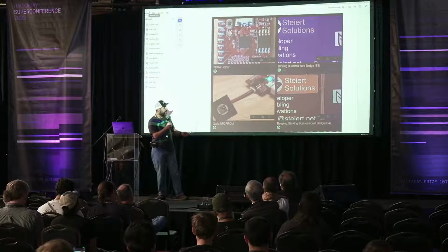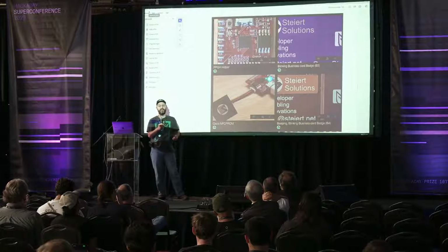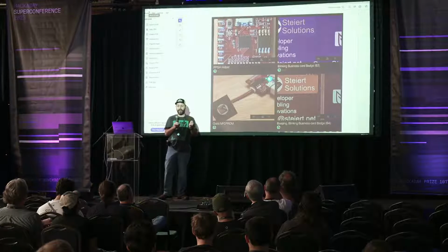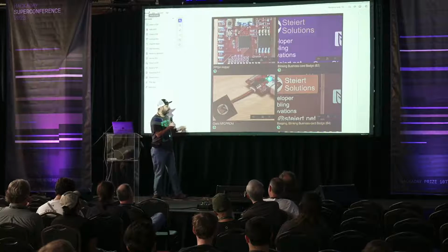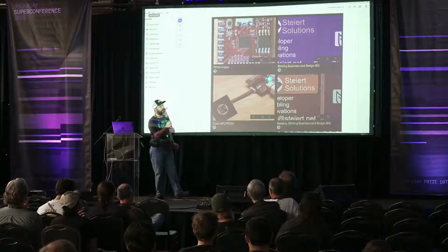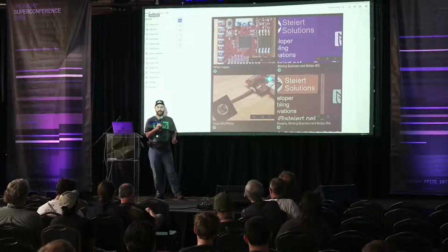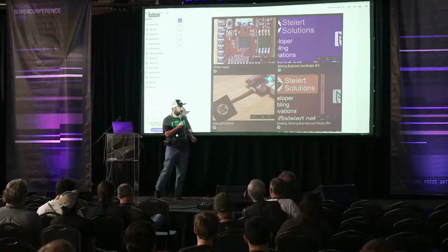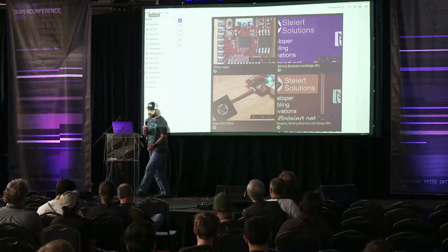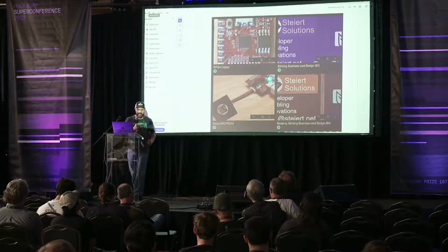But I wasn't just happy with just blinking. I'm like, I can do more with this. So I added beeping. So at this point, I had to go from just an NFC EEPROM that did the power output. The power output was enough to light something up, but I needed to toggle something to get it to beep. So that required a little micro to toggle the bits.